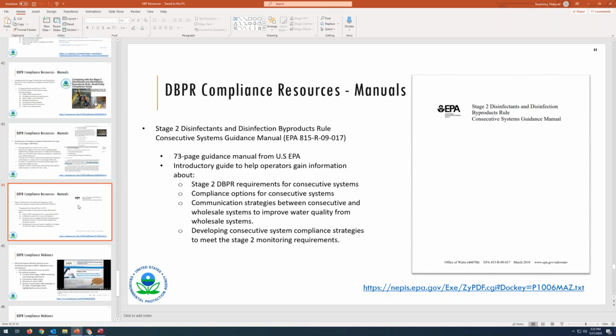I know there are more and more UV technologies like UV LEDs that are being developed, which require less maintenance, and it's cheaper to operate. That would definitely be better than reusing chlorine as your disinfectant source. But again, depending on your source water quality, UV can produce DBPs as well, or complicate other compliance issues. So I would check your water quality, and check with your state if UV is the best option for your system.